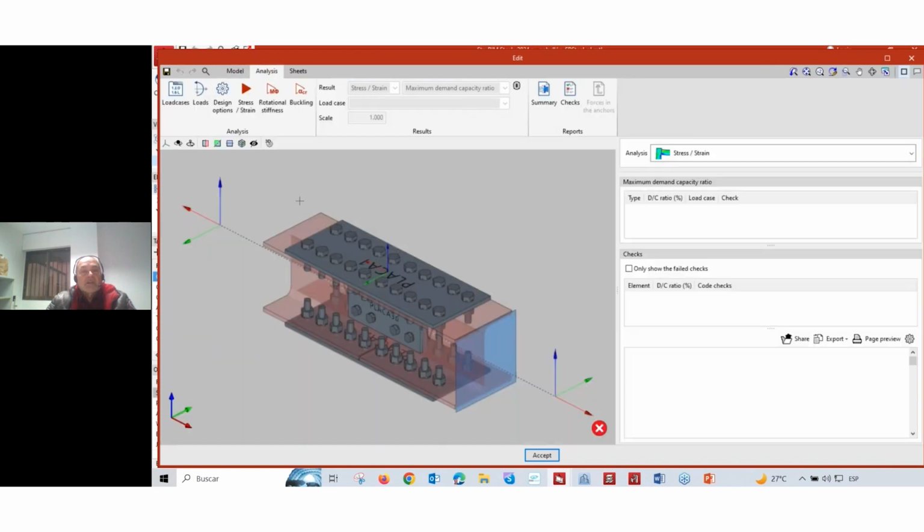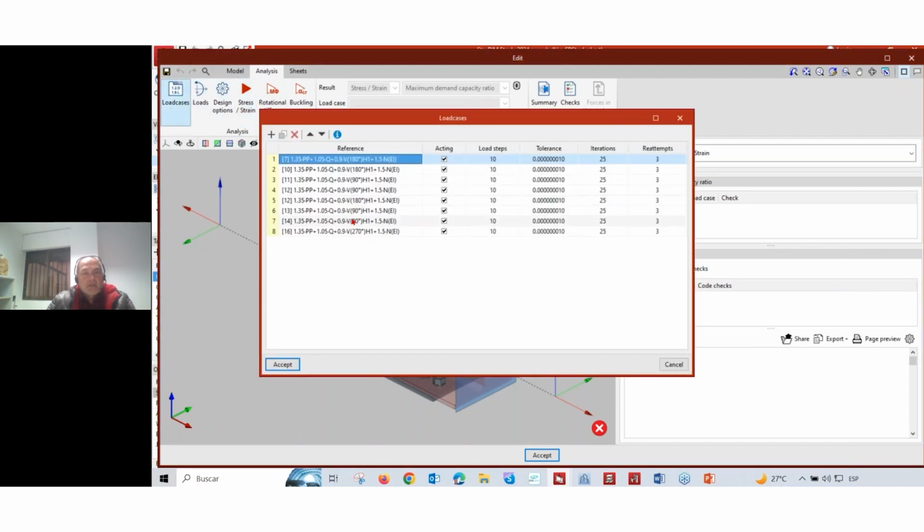Yeah, for the analysis, you can do the stress, but remember the load case scenario. So you have this automatically. There are several steps, just to make sure. Suppose you have the 100 tons maximum load, and you divide that load in several steps. You can divide it by 5.